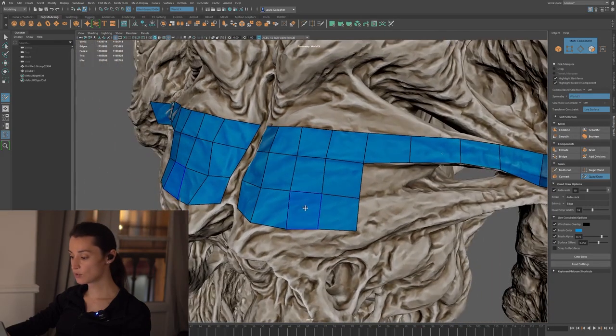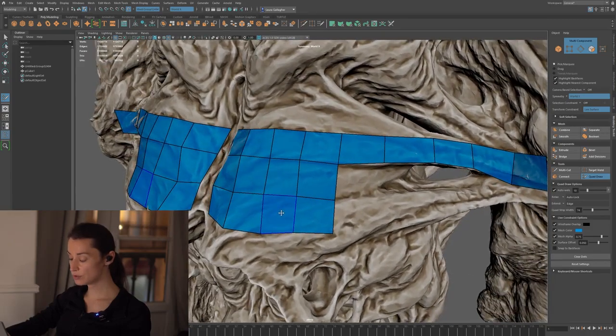So as you can see, Quadra is actually very, very easy to use. Pretty much everything that you do is simply by enabling Quadra here and then using different key combinations to create different effects, whether that is to simply erase stuff, whether that is to simply extrude stuff, create strips of polygons, these sorts of things.